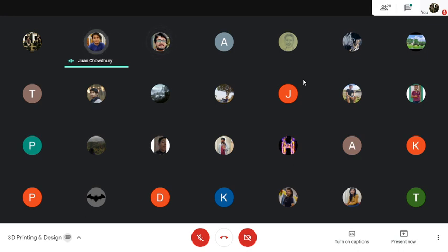So they use this scanner, after which they override with some flat surfaces, just like we do in 3D modeling. They connect some dots, and between the dots there will be a flat surface. That assures that you will have a straight object, and the surface noises disappear. One more thing is that these scanning systems are incapable of penetrating through the object. So if you have a bearing housing where there's a hole in between the object, it will not be able to detect it. So that's one downside.